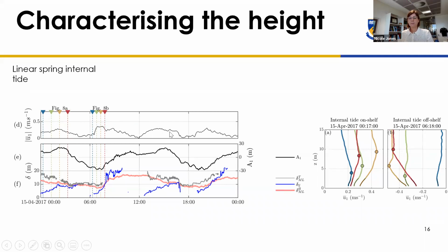But really what I want to show you is that from each of these velocity profiles, we can choose a height of inflection of that velocity profile and form these blue lines here. And so this is a measure really of the momentum boundary layer height.